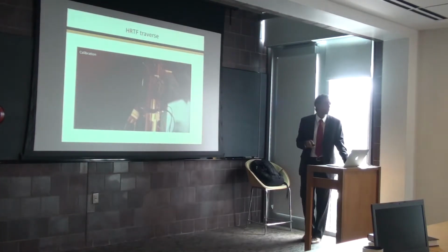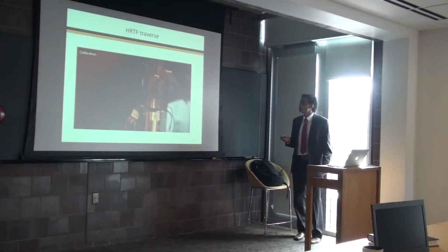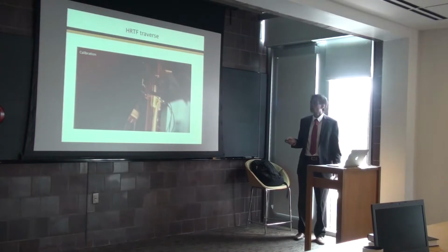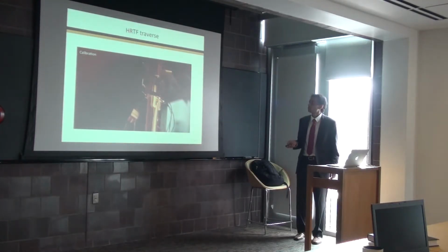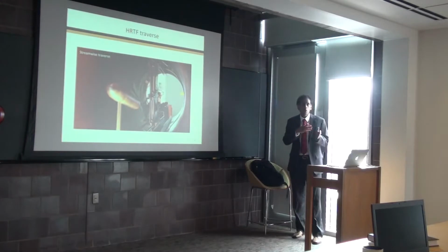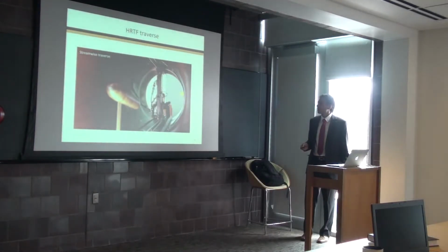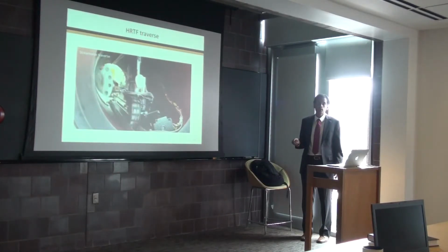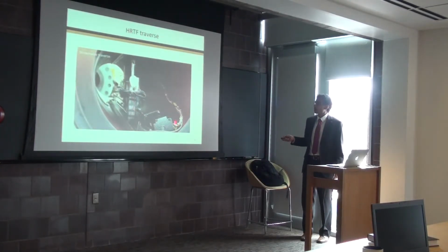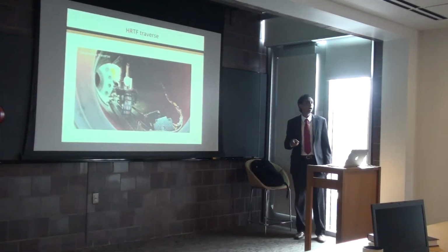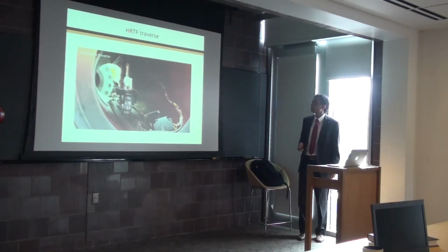We'd like to take a couple of components of the velocity field. So we do that using a so-called crosswire probe, which requires a directional calibration to occur, and this also can be performed using this traverse. And finally, in all of the images that I've showed to you before, we want to look at a wake evolution. And so this is done not by moving the submarine, but by moving the traverse that holds the probe, a rather large streamwise motor, a lead screw, some cabling, 1 or 2 cables that are needed to be able to power the motors and to take the data that we need.